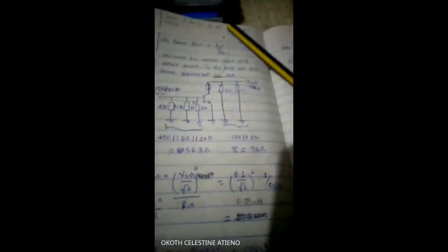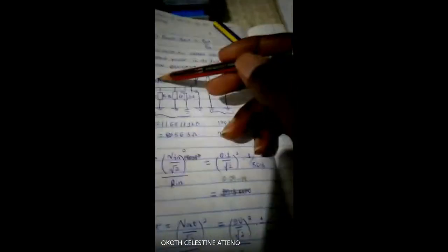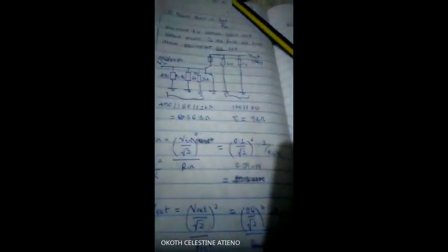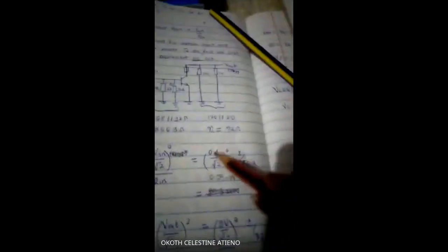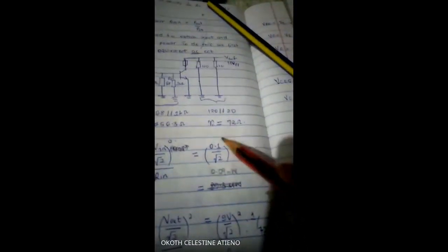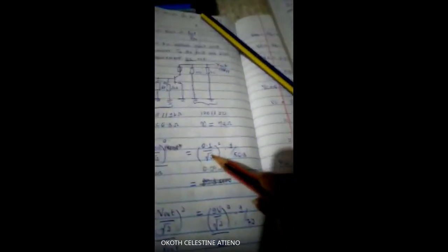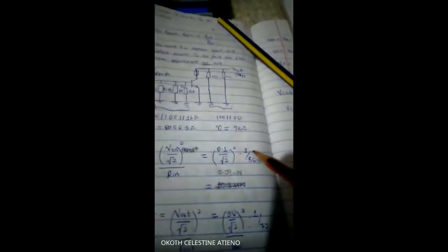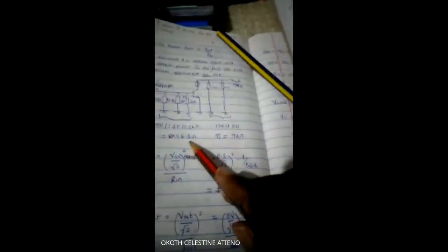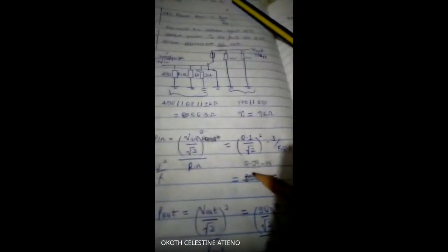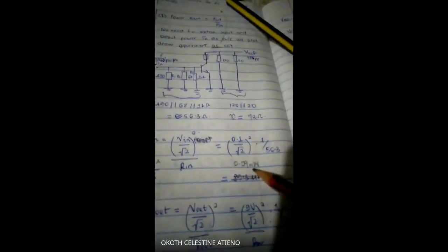But I've noted we're only using peak voltage, not peak to peak. So that will be 200 millivolts, just say millivolts. Divided by 2 is 100 millivolts. If you convert 100 divided by 1000, you get 0.1 squared over root 2 for the voltage, and then times 1 over Rin. So 56.3. I hope you guys are okay till there. To get your power in, it is 0.09 milliwatts.